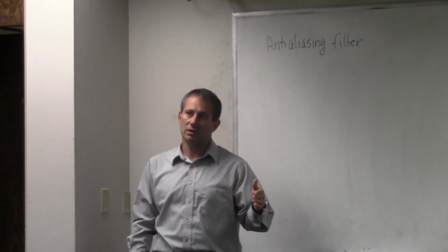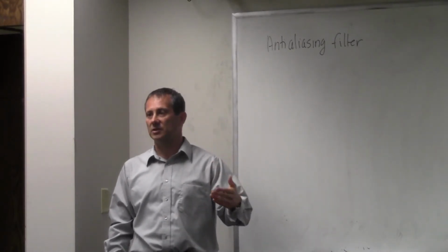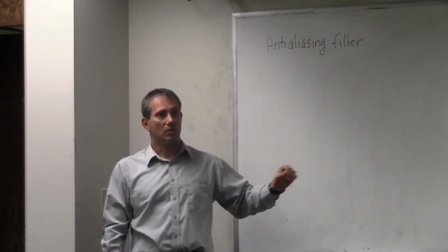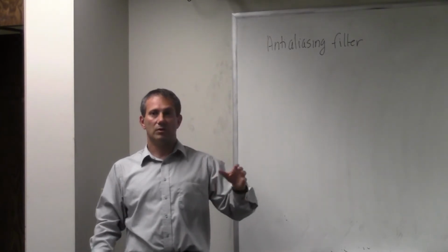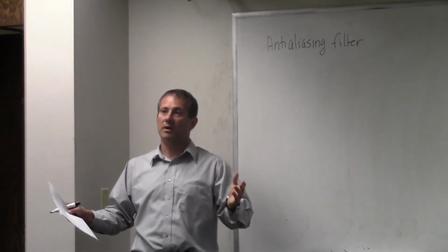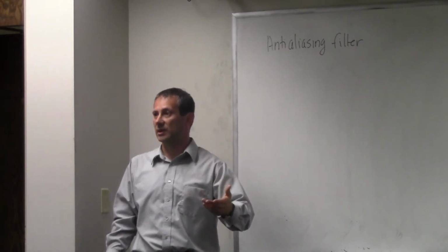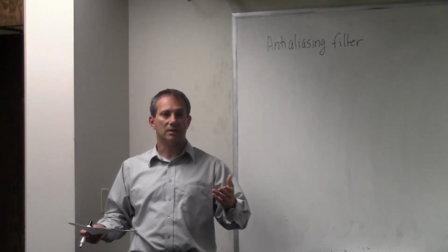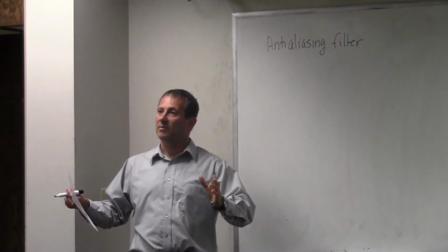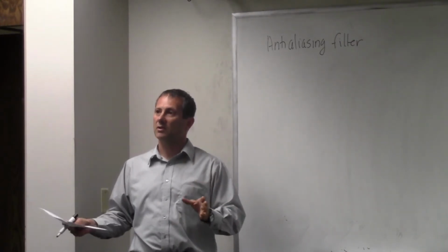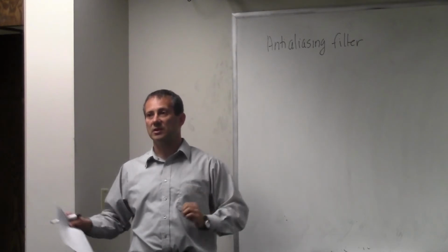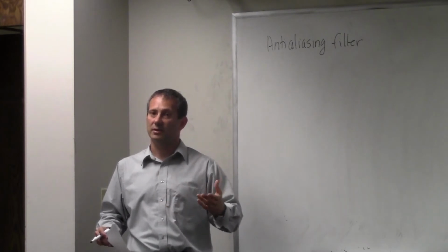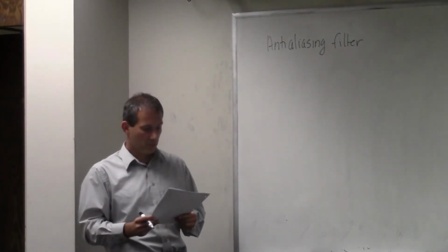Where the cutoff point is depends on the particular application. We know how to do this based on Parseval's theorem, or the energy of the signal. We know that we can determine the bandwidth just from the requirement to preserve a certain amount of energy or power. So, based on experimentation or whatever may be the case, we determine what the bandwidth is. And before we sample the signal, we process it with a filter that cuts off the frequencies above a certain band. This filter we call an anti-aliasing filter, the filter that gets rid of high frequency components.